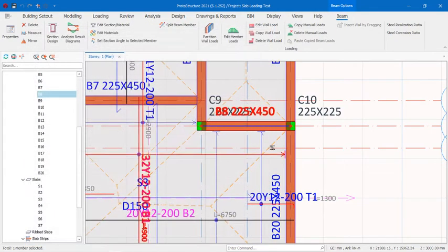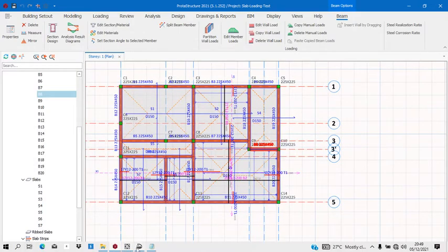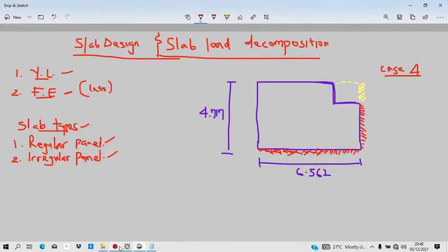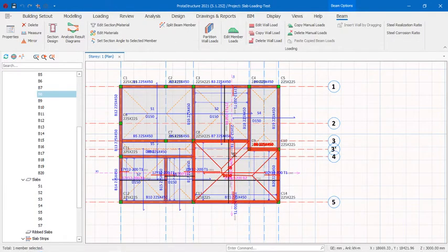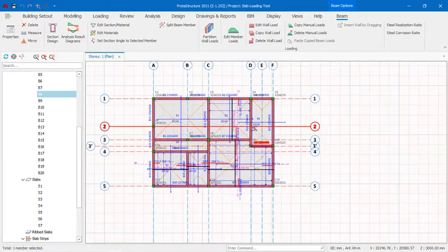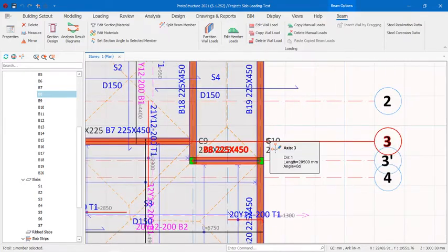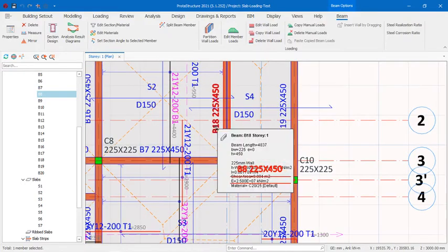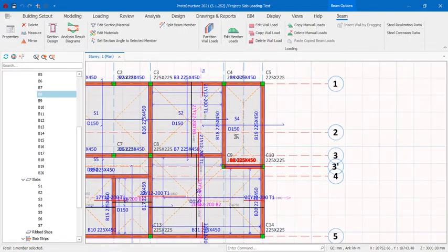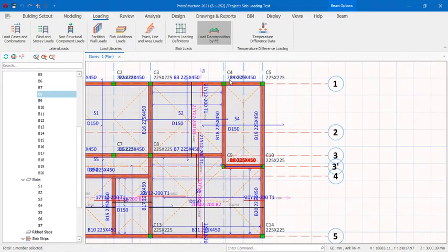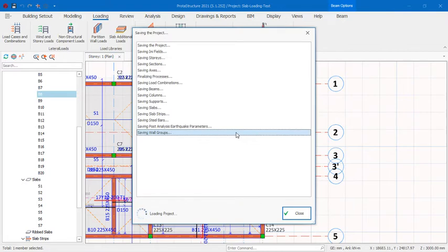So in essence, what I'm saying is that when you run finite element, even in the software, they will tell you the finer the mesh, the better the accuracy of your result. So my advice is that when you are using finite element, it is better you have a finer mesh so that you can have something close to what you have idealized and predicted as the likely result you are supposed to have.